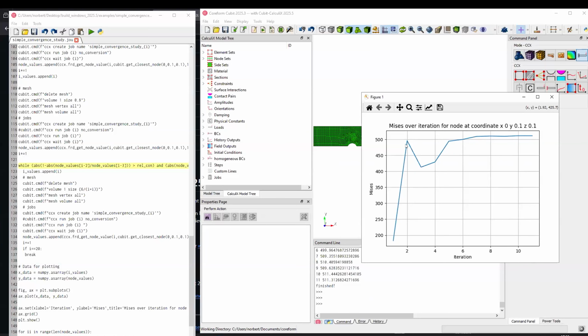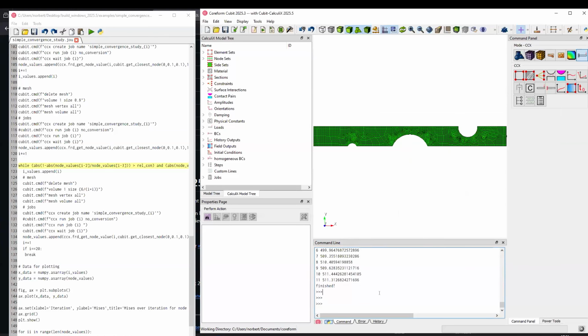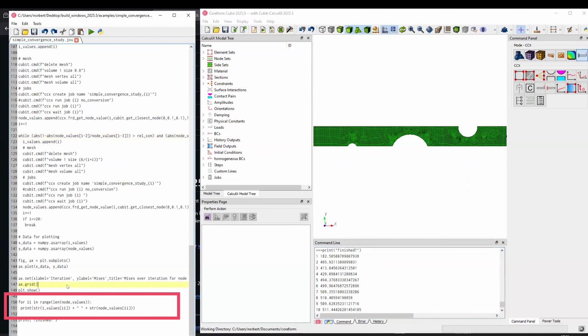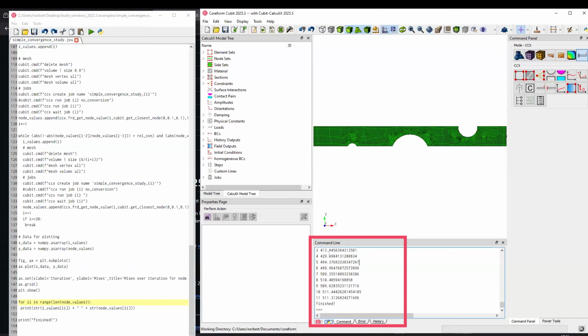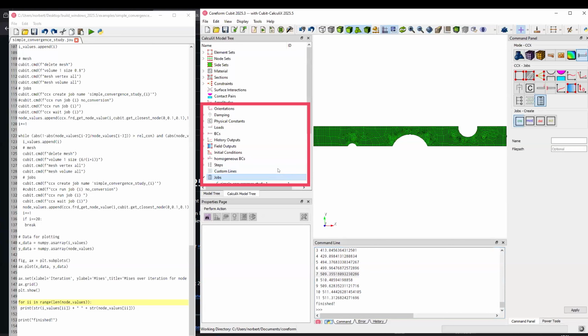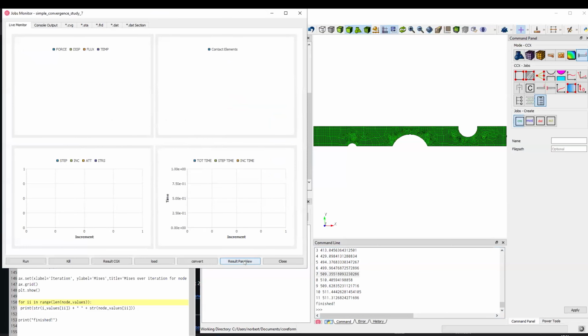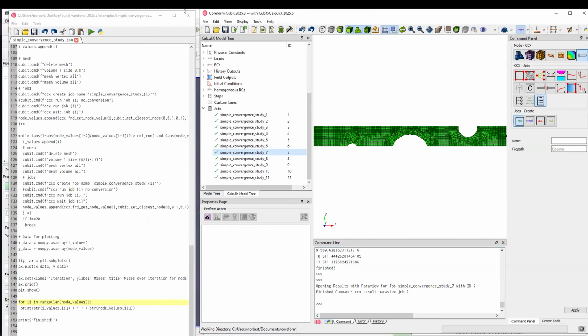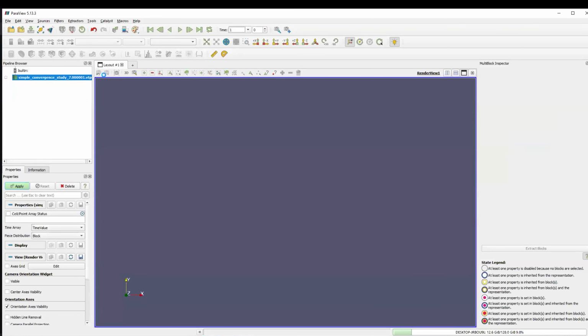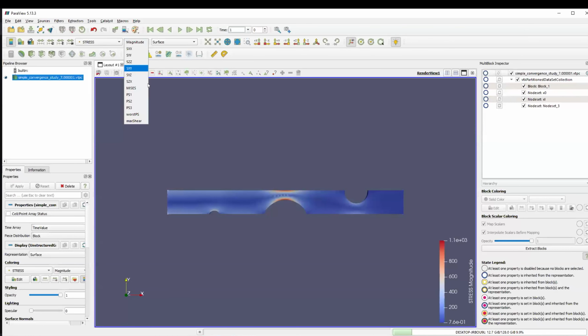So that was the coarsest mesh, that was the first mesh, so the difference was too great, so it took another run. Then I get the more accurate result, and so on, and probably the 7th iteration would be fine enough. And as down here, I plotted all my values. I can see how the value changes with a finer mesh. So I could say, yes, 7th iteration was fine enough. I could then take a look at the results. How this mesh looked.